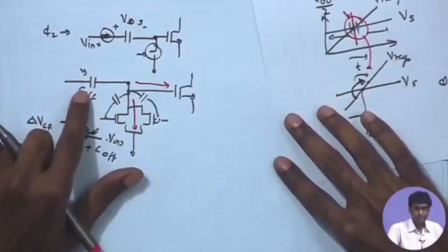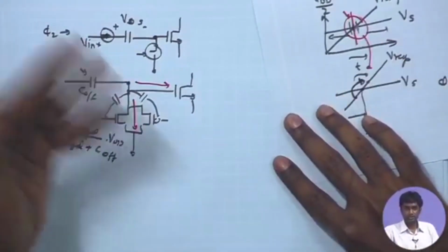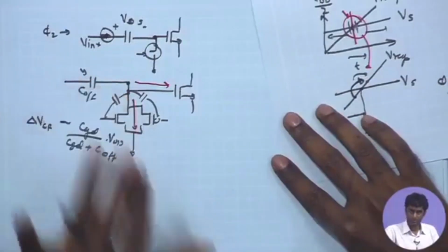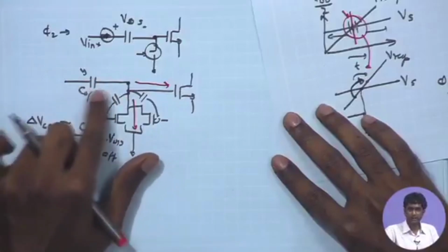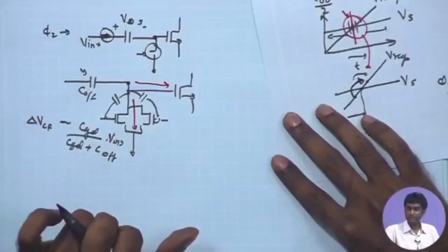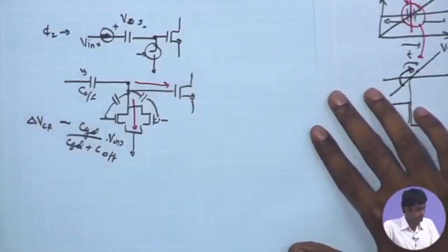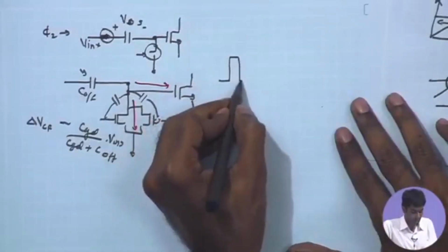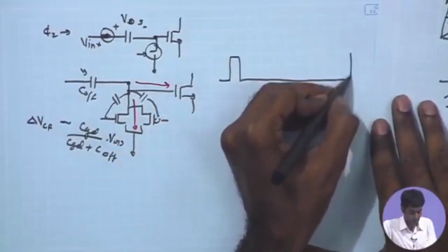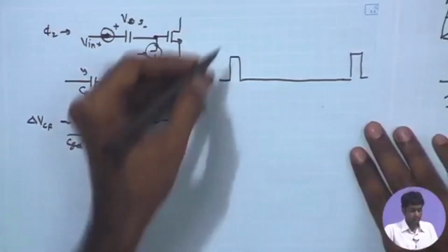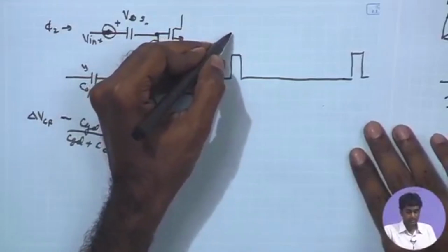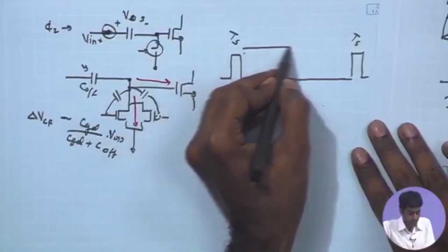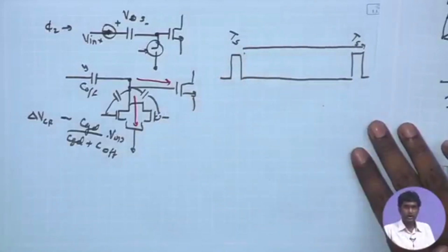Now, of course, the duration of the processing or the duration of the refresh is going to be another important question before we determine the size of the capacitor. So, remember the operation that we have overall for the comparator. We have these sampling pulses T sample, which are possibly coming on periodically with the required sampling rate.